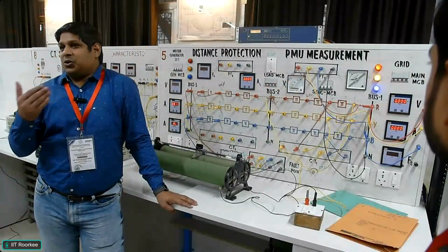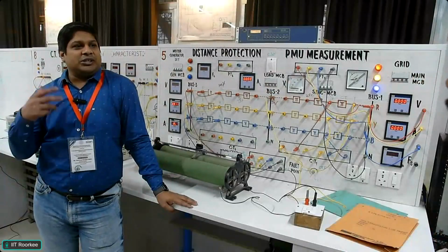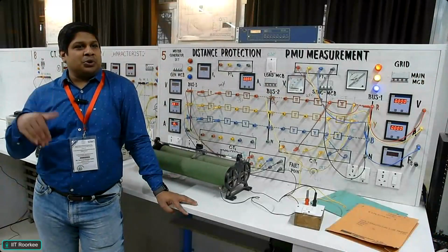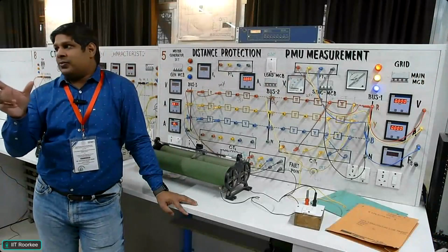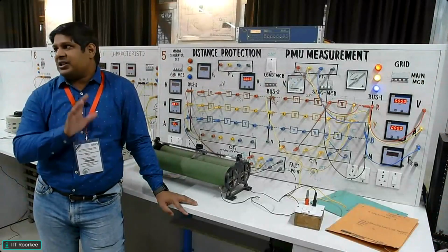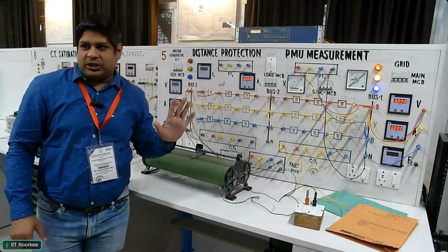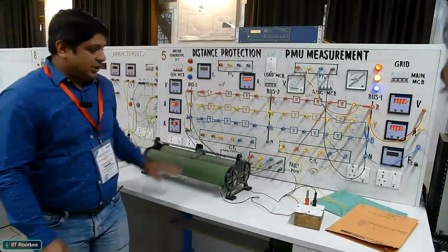As you know, as the number of nodes increases, if you do load flow studies and other studies, the computation capability required should be more. It takes more time to converge. So that's why we generally prefer pi section models. So here we have this pi section. Any doubt until here? So this is a pi section model, different models. And then